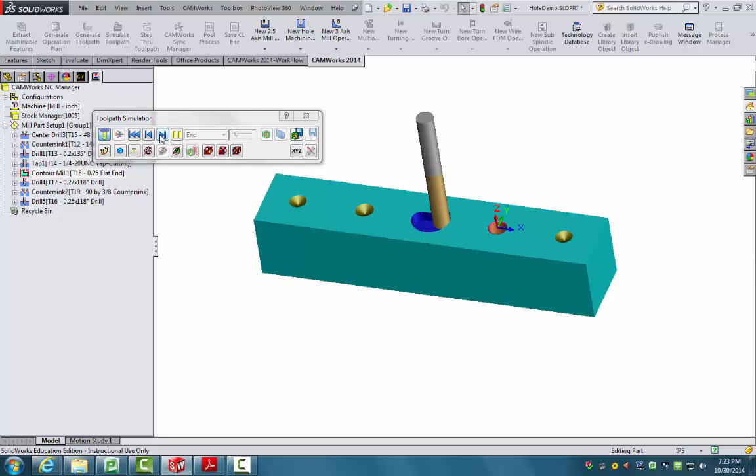Also, you can click, drag, and drop and reorder any contours if perhaps you want to cut out a part at the very end, but you want to do all the detail work before you cut it out, because then it'll become loose in your fixture. That's very easy to do. You can just simply drag them around. The order of operations goes from the top down. So just moving one to the top will make it much quicker. So I'm going to speed this up a little bit.